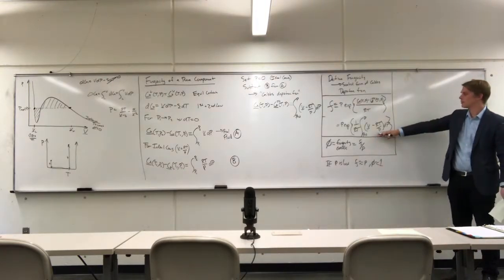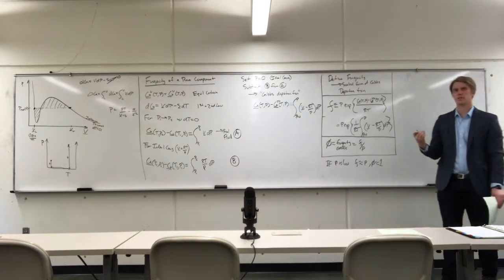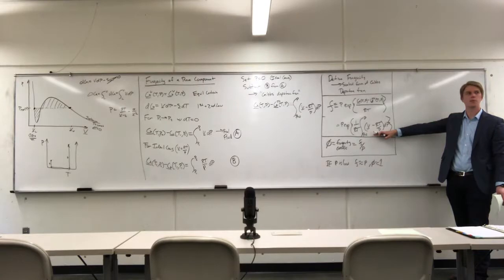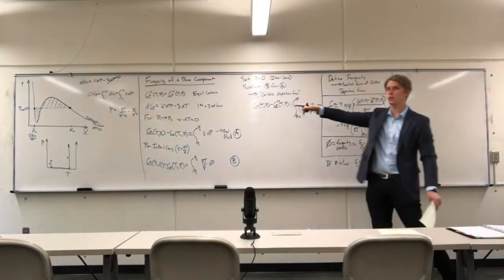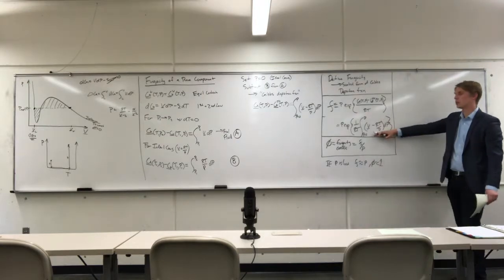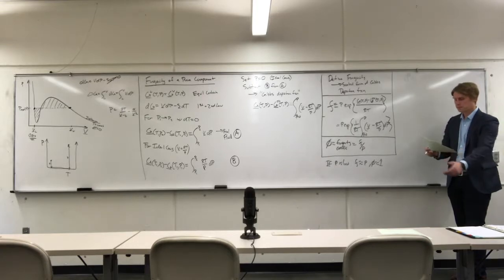So the notion here is that we don't really want to necessarily keep track of every single ideal gas calculation, so the easier approach is just to lump it together and say all we care about is the deviation from ideal gas behavior. But the true purpose of the fugacity comes with multi-component systems. For single component, it's convenient to introduce the concept, but it's not critical. We can solve phase equilibrium without the fugacity for a single component system. It's much more difficult to solve phase equilibrium for a multi-component system without the definition of fugacity.